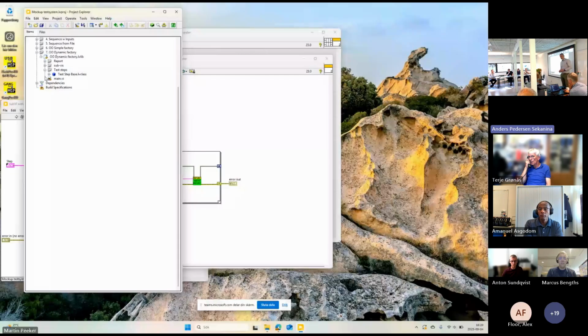But obviously, just having DQMH is going to make your project explode. Just doing a call or something like that is going to add 5 different functions for you. So if you're afraid of a lot of VIs, don't go for any framework at all. That's my suggestion. But the frameworks do help, and you need to feel at ease with knowing, okay, this is part of the framework, I don't need to care about that. I wish there were better ways in the projects to hide that away somehow, but it's going to be in your face all the time.